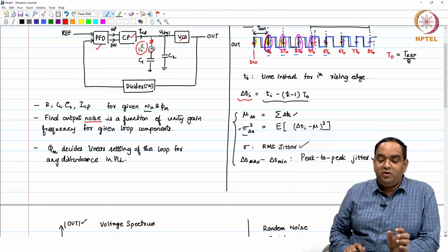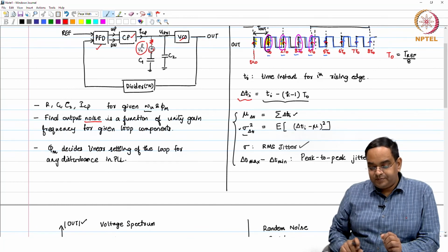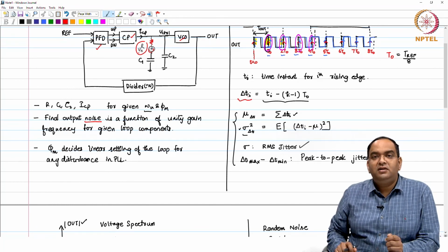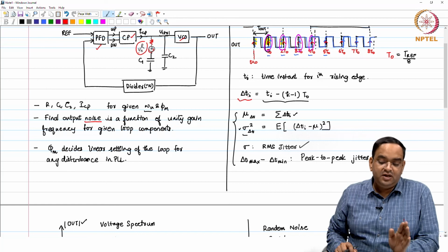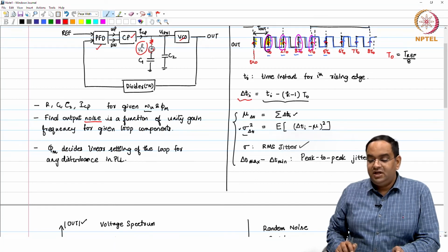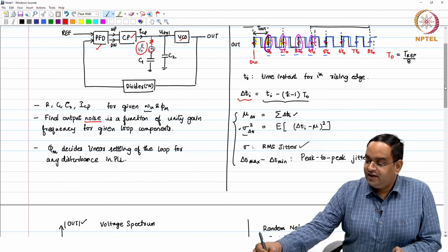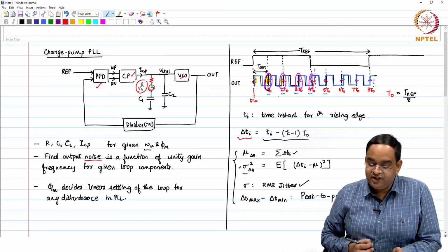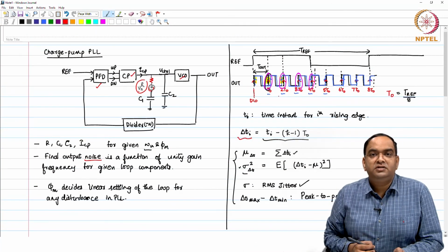We designed a PLL using transistors, capacitors and resistors. Capacitors have no noise associated with them, even in the regular technology which we use. So, resistors and transistors are the noise sources. They create disturbances and perturbations and the output clock jitter.